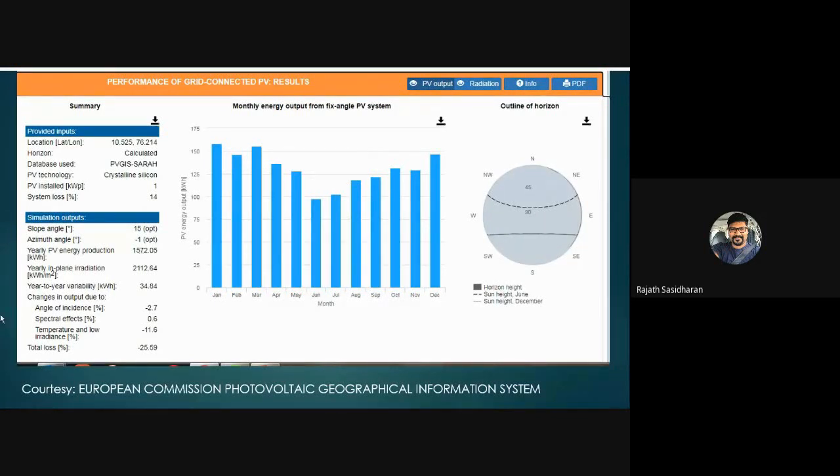Let's come back to the point itself. So in this tool, you can also see how the distribution of energy is done, right? So this is done in Thrissur. So the June and July, when the monsoon season comes, the energy is very less because it's more or less cloudy days. And you can see January and December and February, March, all these months, the irradiation is very good. There is too much shining sun, and hence it produces a good amount of energy during that time, right?